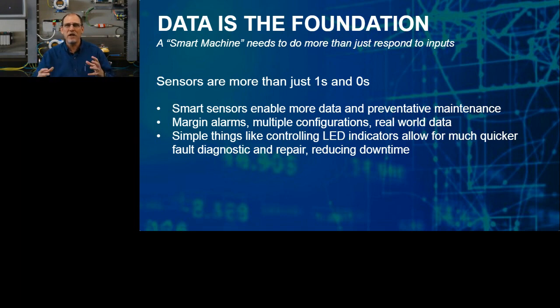Every time you wanted to make a new run of a product, you had to adjust these cams. And so we developed what we call an e-cam, or electronic cam. It was basically just a sensor going past a dog that would trip it. And then you could adjust timing in a PLC. That was the first step in my career of saying, oh wow, automation can really change your life as far as setup goes. Because at that time, we were running short runs of things, so you had to do a lot of setups. Well, you can take that and put that in a library and have your equipment automatically adjust to things.